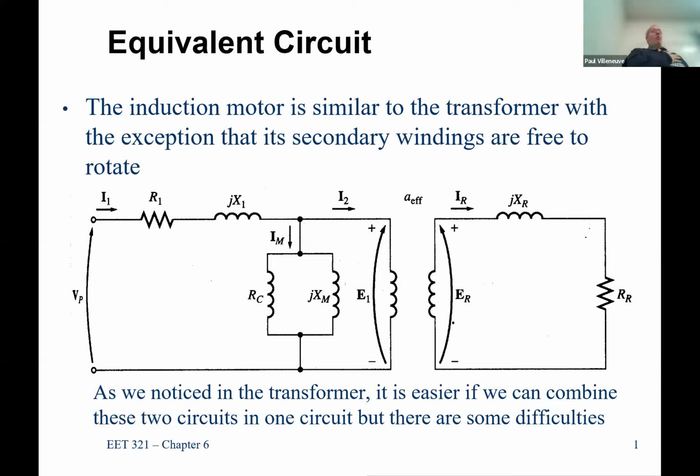Whether it's a wound rotor, where we're injecting three-phase AC currents into the rotor circuit, or it's induced, where we get actual AC current flow because we have coils of wire and a changing magnetic field, we induce a current, and that creates a magnetic field. In either case, it's going to have an AC set of windings.